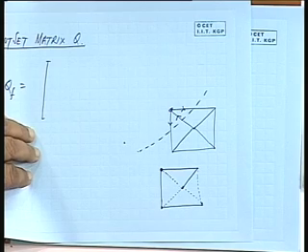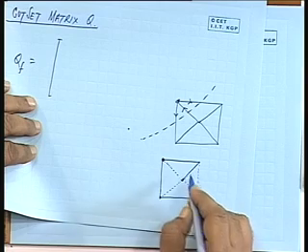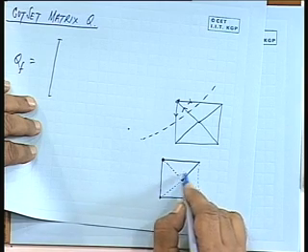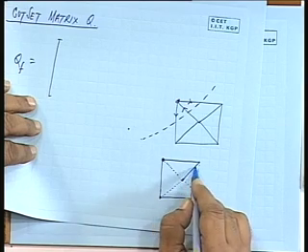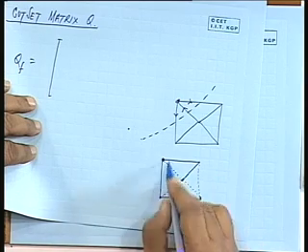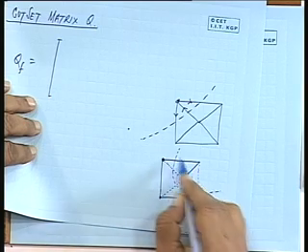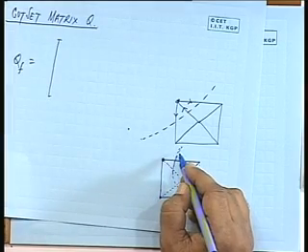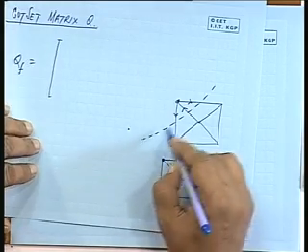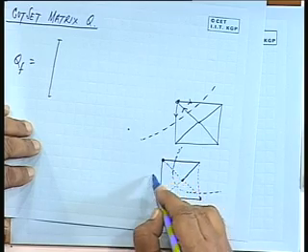Is that all right? So, if I want to have a cut set, how do I cut this? Suppose I want to isolate this. So, this can be a cut set, is it not? I will cut one twig at a time. So, this will not be a possible cut set if I choose the tree like this, because two elements of the tree will be eliminated.